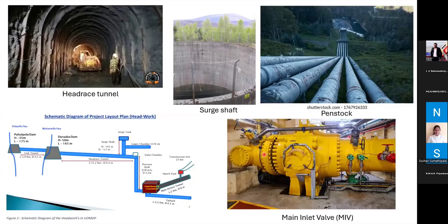That means if you do that task, due to the immense pressure of the water, most probably the MIV will be out of service. You have to replace the MIV after that operation. Because the water pressure is really high, the MIV is operated only when we want to do some maintenance in the generator. When the water is stopped at the generator locally, we can close the MIV.